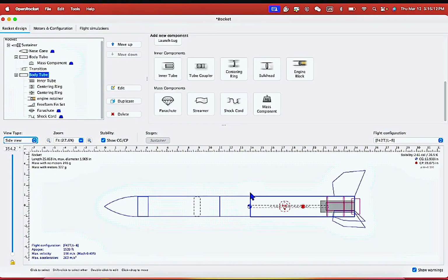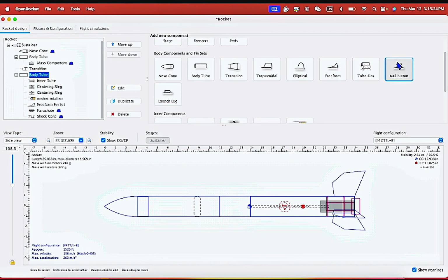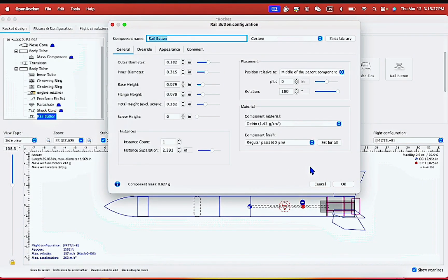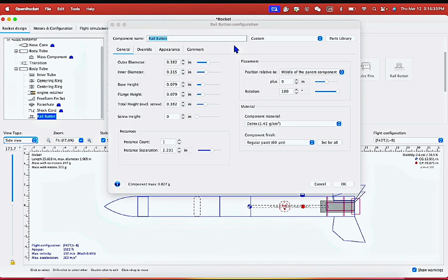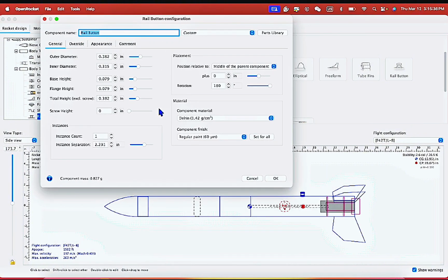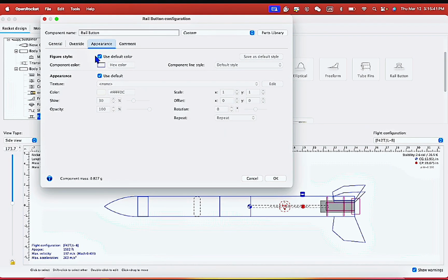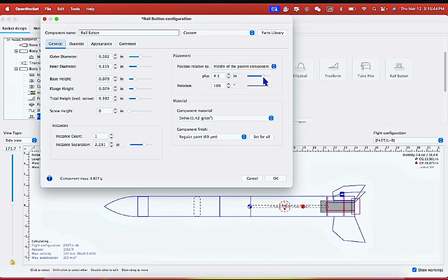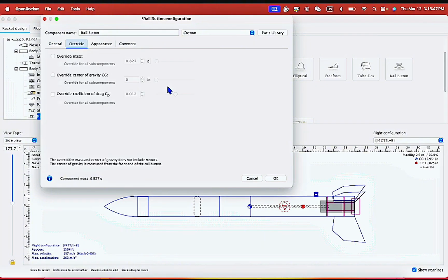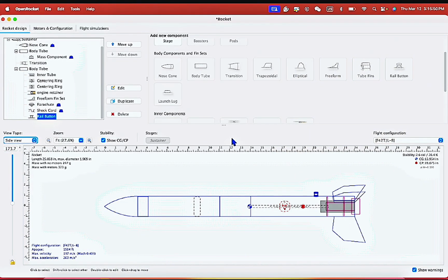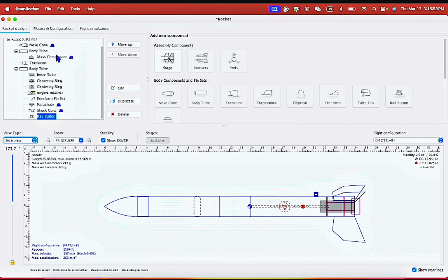Right, and then basically this entire rocket, technically it's ready to fly, but right now it's not because we haven't added any motors or weight yet. And also another really important thing is called the rail button. Usually we have a launch rail, which we 3D print and made ourselves, but OpenRocket only supports rail buttons or launch lugs, both of which are not the rail guides we want. And basically, for these, the best you can do is just set the position of these, and then override with the weight to be very accurate for your rocket build. Alright. Next, if we want to fly it, alright.